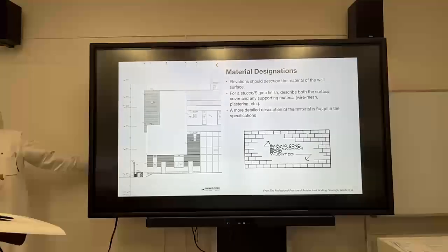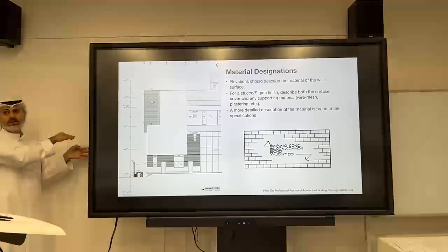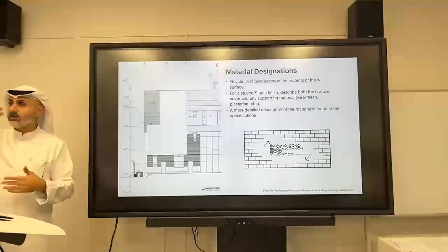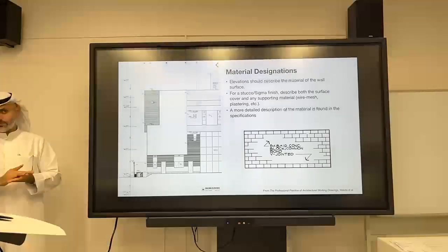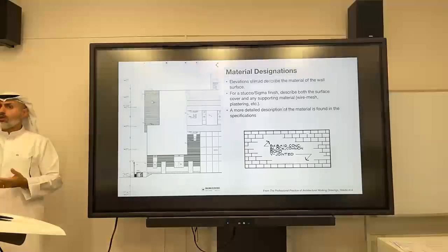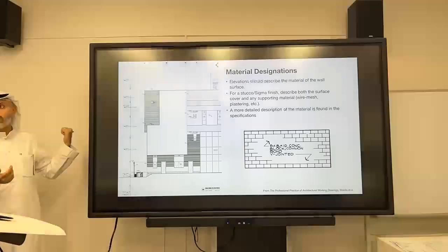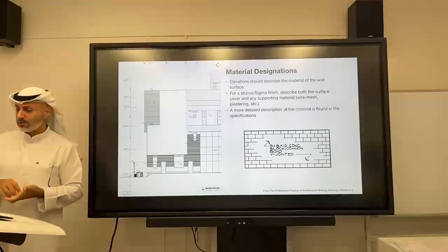The traditional way is like ceramic. Basically just the material with the cement with nothing holding it in place. Which is riskier, especially if you have, for example, a facade, it could fall. And you'll notice along the streets, when you go around, you might see some pieces of stone falling off buildings. That probably has to do with the way it was installed, maybe not in the right way with a semi-mechanical system.